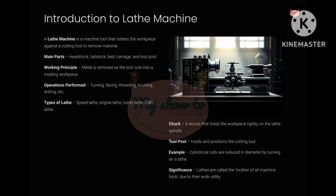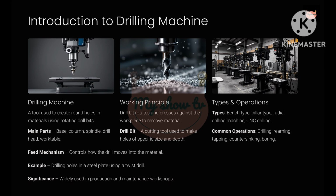Some common operations include turning, reducing the diameter. Facing, creating flat surfaces. Threading, cutting threads like those on a bolt. Lathes are of many types, from manual engine lathes to computer-controlled (CNC) lathes. An important example is stainless steel shafts made via turning and facing. The lathe is often called the mother of all machine tools due to its versatility and ability to perform many basic operations.